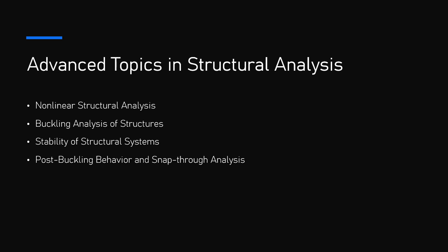1. Mechanics of snap-through. Snap-through occurs when a system's load deformation curve has two or more local minima, representing stable equilibrium points. The structure starts in one stable configuration and, when perturbed beyond a critical point, snaps to another stable configuration.